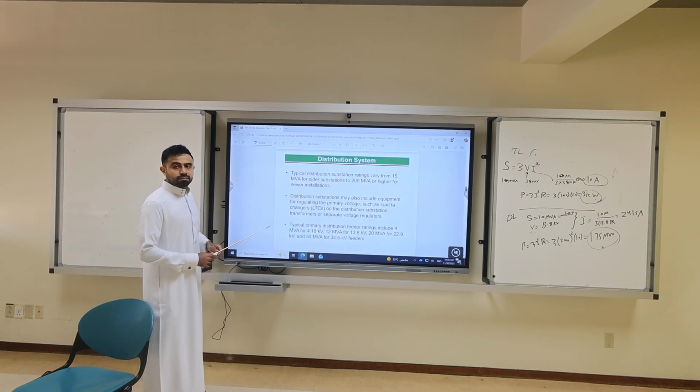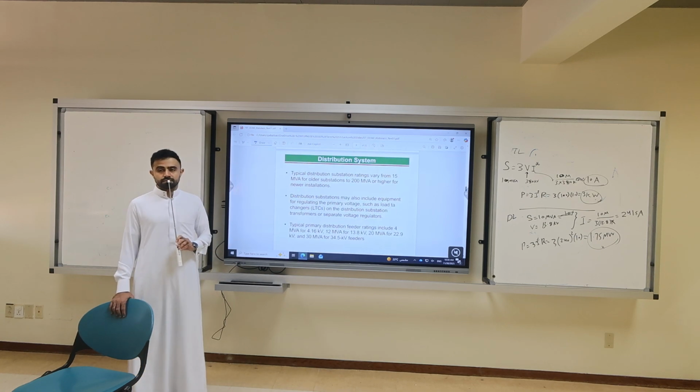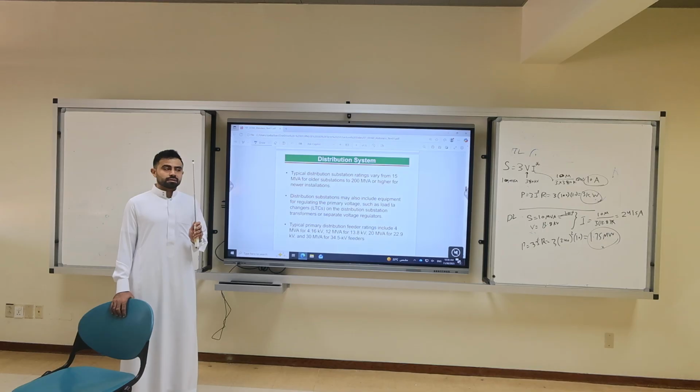Doctor, are the harmonics here the same as the frequency range we were talking about, between 59.8 and 60.2? No. Harmonics: 60 times 3 is what? 180. Yes, 180 hertz will add up and change the original 60. For the fifth harmonic, it's not 60, it's 5 times 2 pi 60.